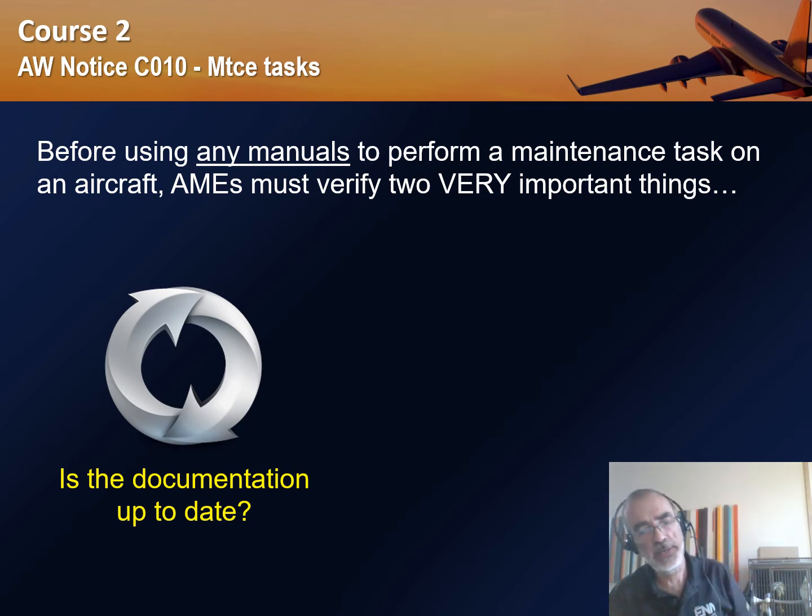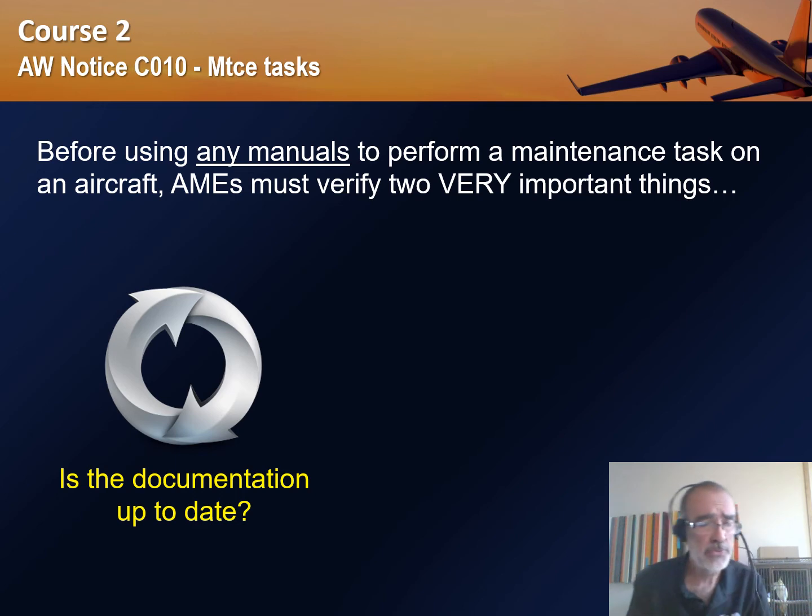When I was at Air Canada, we still had some paper copies of some maintenance manuals, and when you signed a maintenance release, you had to add a note saying the maintenance, testing and certification was performed as per manual, this number, and you had to state the revision date, meaning if something happens, they can trace back to whatever maintenance manual version you used.